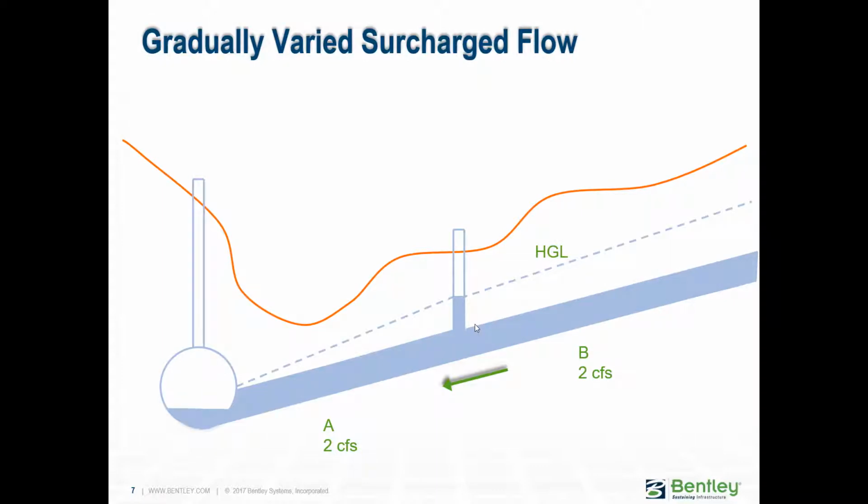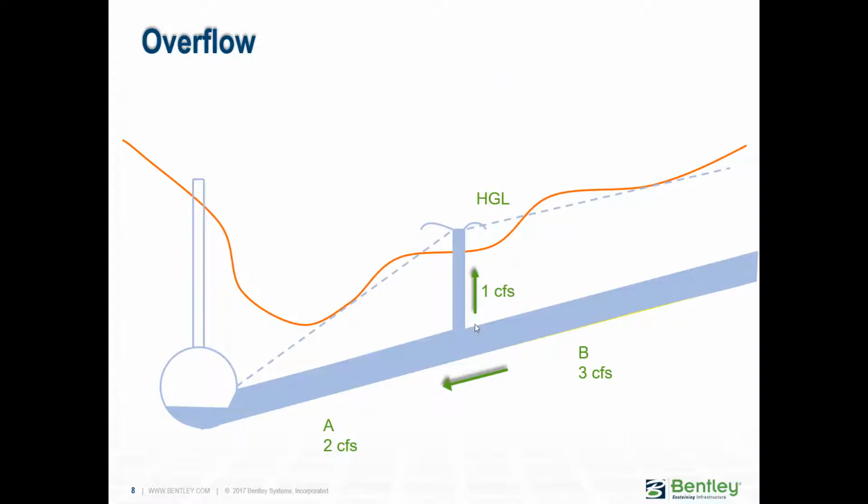So in situations when you have surcharged flow, it is necessary to solve more complex equations because now you don't have normal depths anymore. One of the things that could be challenging if you were to do this by hand is that the flow transitions between free surface flow and pressurized flows. So you'd have to change the equations that you're using. So that's why I think programs like SewerCAD are so useful.